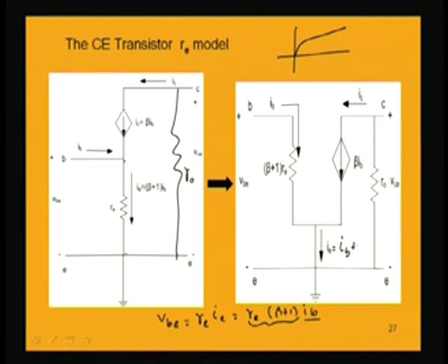So, IB plus IC is here, and this is a far better circuit than this, because our main problem was at this point these two are joining and this current is not IB, it is IE. So, it would have led to some difficulties in analysis. So, we have conveniently removed the difficulty by drawing the circuit in this fashion, and it will be now easy, because you can now notice that input and output circuits we are conveniently separating out. So, this is done by writing the equivalent or reflected resistance for this RE, which is nothing but (beta plus 1) RE.